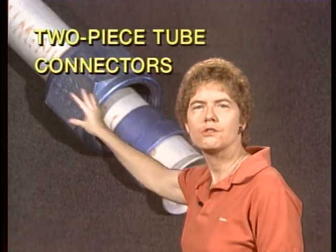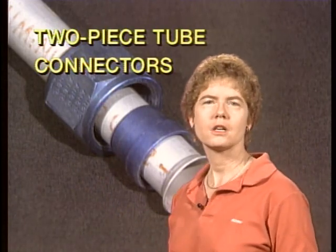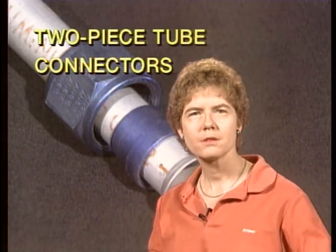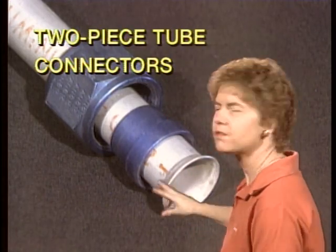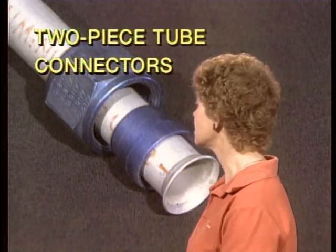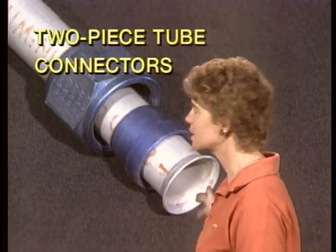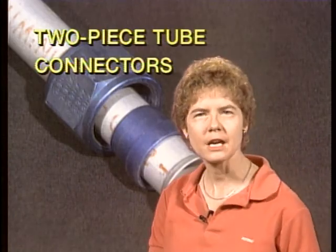And that's what you use when you're making a tubing flare, because what that type of connector does is eliminate the possibility of reducing the flare thickness by wiping or ironing when you're tightening it down. The use of the sleeve and the connector keeps that flare intact when you're tightening it down.